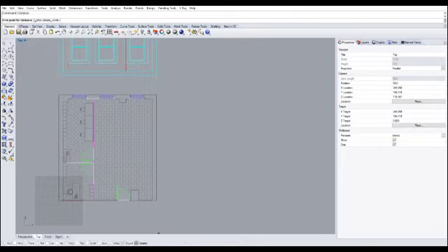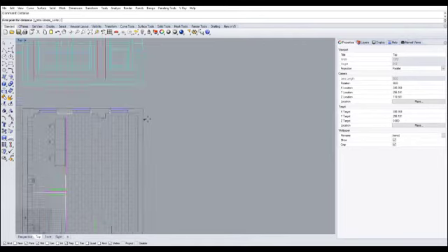It's off by default, so you should turn it on by clicking on it, and it will highlight for you. And once you click on it, just like AutoCAD, it's got these different snap settings that you should turn on for your convenience. So in Rhino, you should almost always have end, point, mid, perpendicular, and of course vertex on. Once that's on, we can use the OSnap to measure our walls.